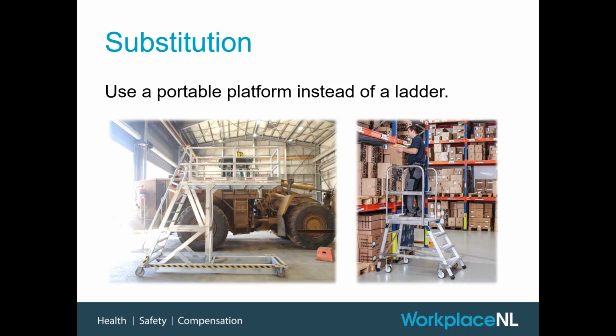Again, there are practical elements to this. These portable platform systems take up a lot more space than a portable ladder. That's one issue. But they do come in a lot of different designs and variety, and you can get these for multiple workers, and sometimes that's what you need. Obviously with a ladder, it's one worker at a time, but if you need a few hands up doing a thing at height, these portable systems can be quite handy to have.